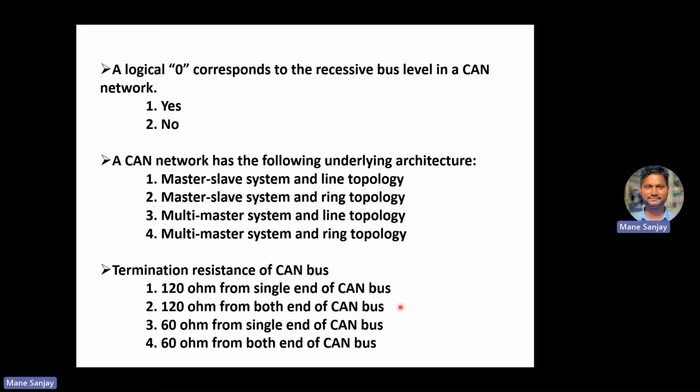Keep in mind that when you go to the vehicle and look for the termination resistance, always switch off the power of the vehicle. Do not switch on the ignition, and do not keep the battery connected to the ECU. Keep everything off. Make sure that the ECU is not getting power. Then use your multimeter, turn the multimeter to resistance, and probe CAN-H and CAN-L and check the resistance. Ideally, it should be 60 ohm, but practically you can get values ranging from 50 or even 57 ohm to 61 or 62 ohm. If that is the value, that means your network is perfect. There is no error in the physical network. If some other value comes, like 40 or something, that means there are multiple 120 ohm, or three 120 ohm termination resistors in the network. As three get in parallel, the resultant value changes accordingly. So make sure that you get 60 ohm. Practically 56, 57 or 61, 62 is good enough.